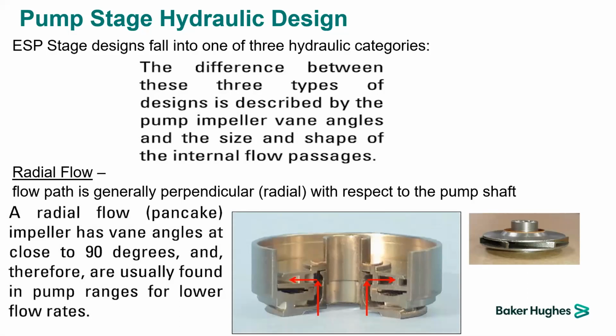Okay, the radial flow handles almost 10% of gas into the pump. So if you have a well condition with almost 10% free gas, radial flow can handle that gas without the need of a gas separator. But if the gas in the pump is higher than 10%, radial flow will not be able to handle it without the help of a gas separator or gas handling device. Okay,